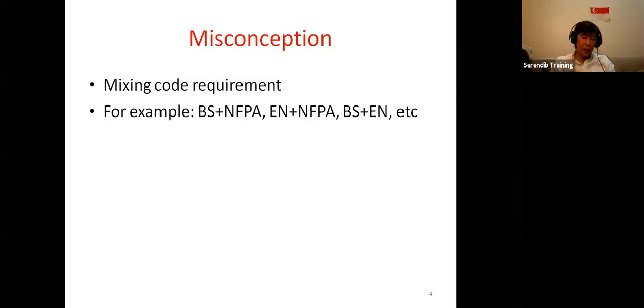So as a designer, you need to just pick a particular standard. Obviously, the driving factor here is the authority. If the authority has assigned NFPA as the main standard or code, then just stick to it. You don't have to move to other standards. This is my opinion, unless you feel NFPA does not address certain systems.